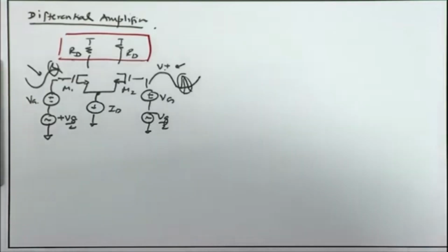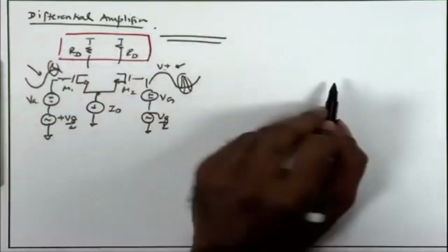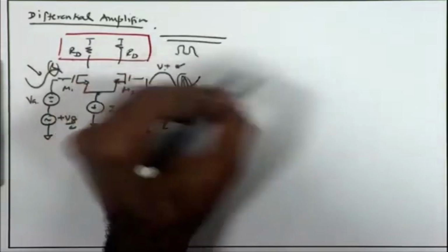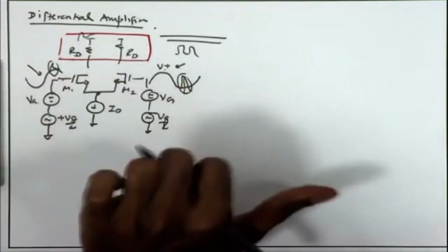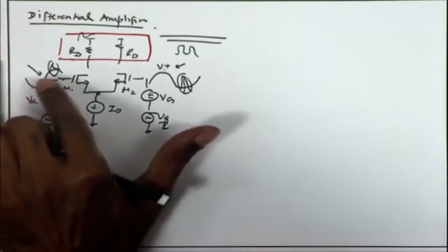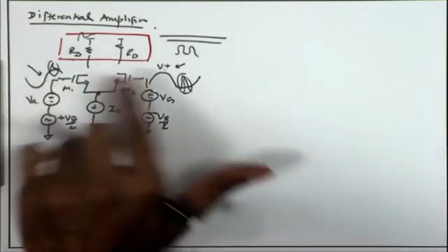Especially when we are going towards SOC, we are trying to integrate analog and digital together. Apart from the external noise sources, there are many other on chip noise sources that can come into the picture. Along with the digital circuit you can have some clock signal going nearby and it can create some common mode noise. The VDD can have some noise. All those appear as common mode noise, and a fully differential circuit operation can reject that common mode noise.